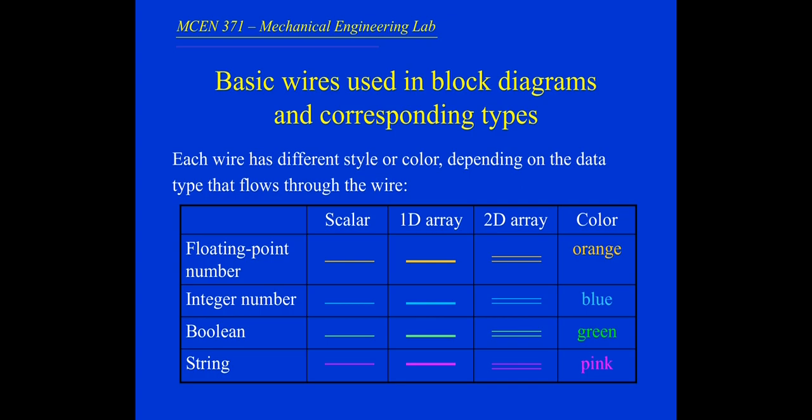When you connect these nodes, you have to connect them with a special kind of wire, because there can be strings with text. So you connect with this violet wire, and with green it is boolean, on off, true or false. Integer numbers have blue, and floating point numbers have yellow.